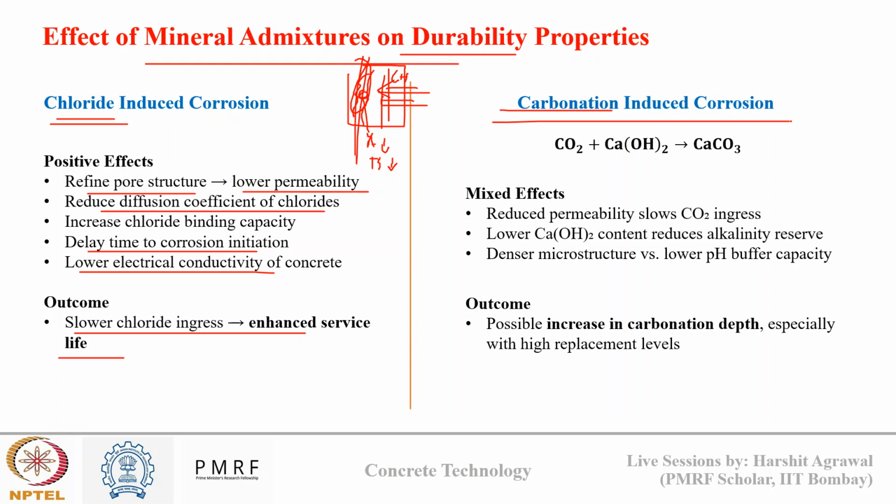Similarly, for carbonation, effect of SCM is mixed. Okay, so what happens? CO2 is not causing any disruption of passive film. However, it consumes Ca(OH)2 which is present in the pore solution and it forms CaCO3.